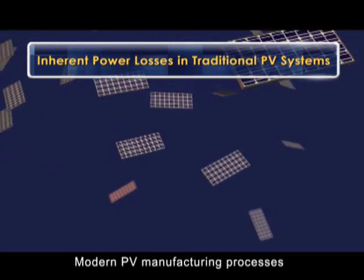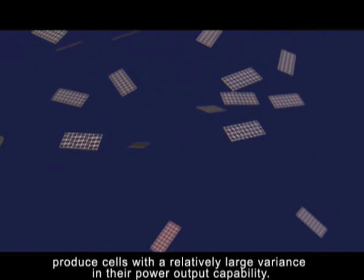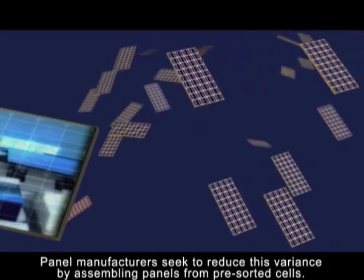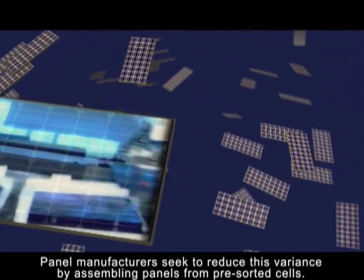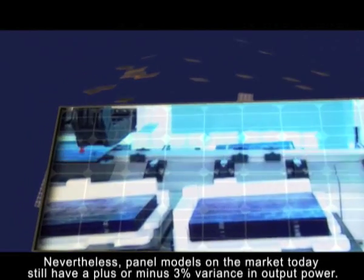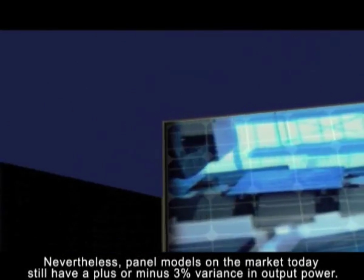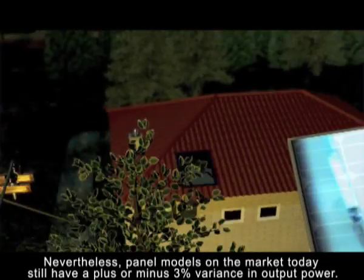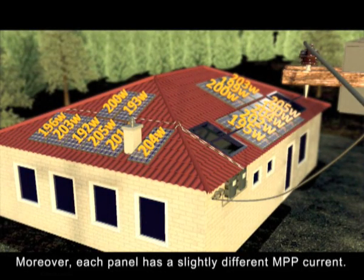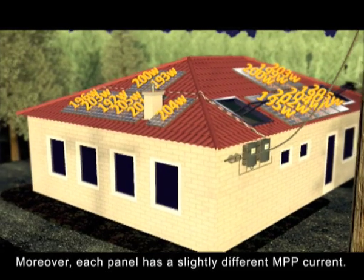Modern PV manufacturing processes produce cells with a relatively large variance in their power output capability. Panel manufacturers seek to reduce their variance by assembling panels from pre-sorted cells. Nevertheless, panel models on the market today still have a plus or minus 3% variance in power output. Moreover, each panel has a slightly different MPP current.